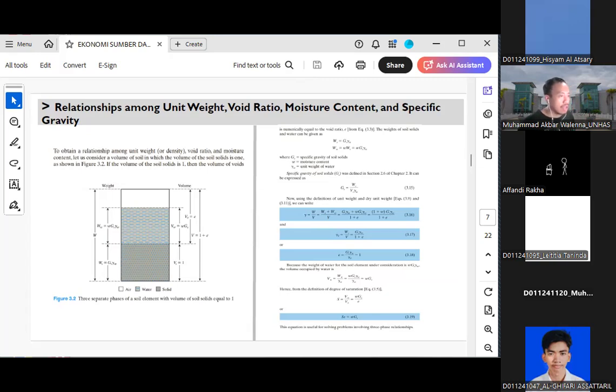Okay, what else? The one below: dry unit weight. Dry unit weight is the special case when there is no water, as I mentioned before. You can notice in the formula that it depends only on the solids and the void ratio. If the soil is dense, in which case e is small, that's when the dry unit weight is high. Okay, what's next?